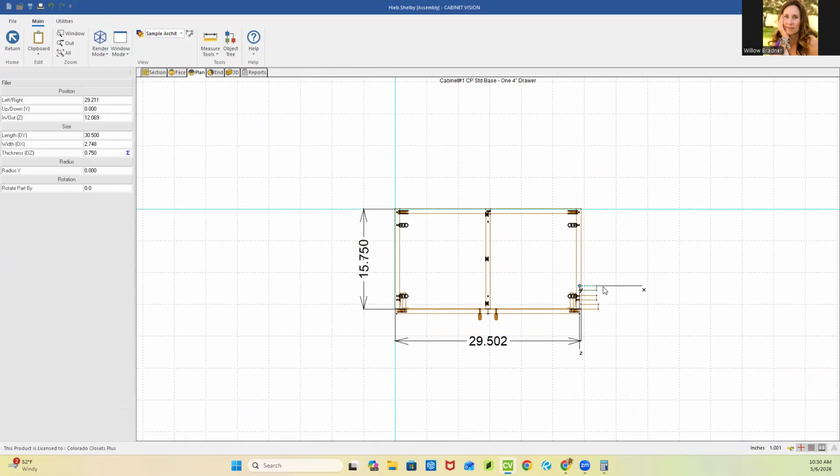It doesn't really matter where they are, because what we just want is for them to be machined and sent out with the guys. This gives them some wood that they can chop up on the chop saw and put a little backer in here, just to make this filler a little more rigid. So it's not just a 3/4 inch little rip of wood that's pinned in with a few pin nails. And sometimes they want to fill the top of the gap in too.